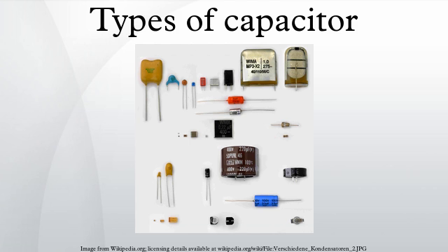A ceramic capacitor is a non-polarized fixed capacitor made out of two or more alternating layers of ceramic and metal in which the ceramic material acts as the dielectric and the metal acts as the electrodes. The ceramic material is a mixture of finely ground granules of paraelectric or ferroelectric materials, modified by mixed oxides that are necessary to achieve the capacitor's desired characteristics. The electrical behavior of the ceramic material is divided into two stability classes: Class 1 ceramic capacitors with high stability and low losses compensating the influence of temperature in resonant circuit applications.